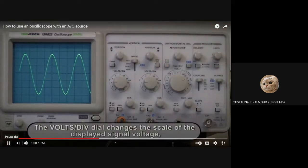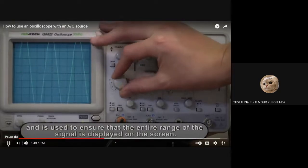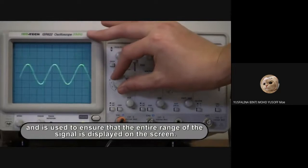The volts per division dial changes the scale of the displayed signal voltage. Okay, so for this one, it changes the scale. Here they put 1 volt, right? You can see it pointed to 1 volt per division, so one box here is 1 division. Later you can see when you change the knob here, the graph also becomes different. The size of the peak also becomes different. It can be used to ensure that the entire range of the signal is displayed on the screen.